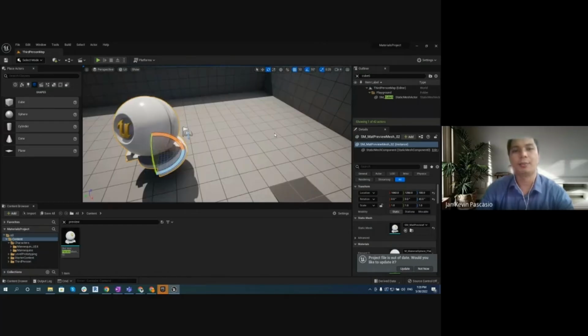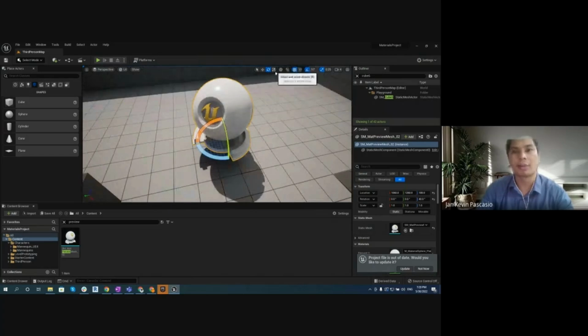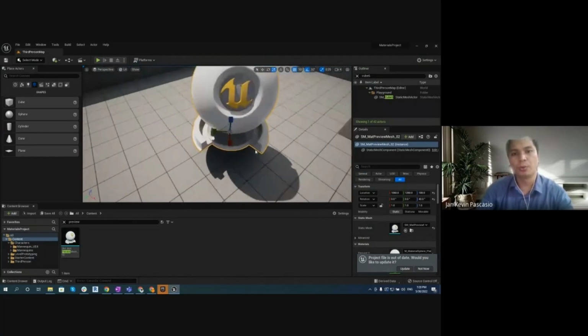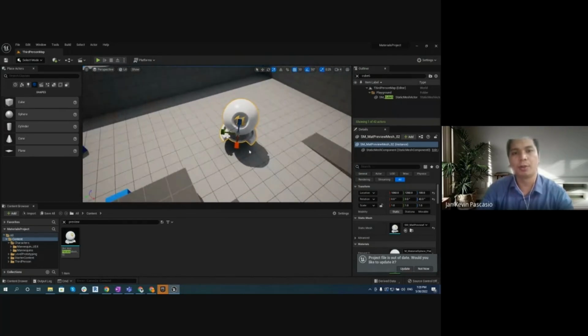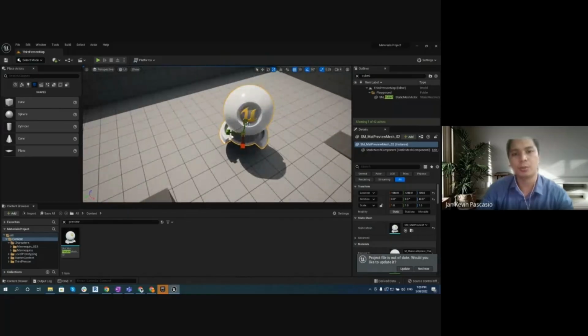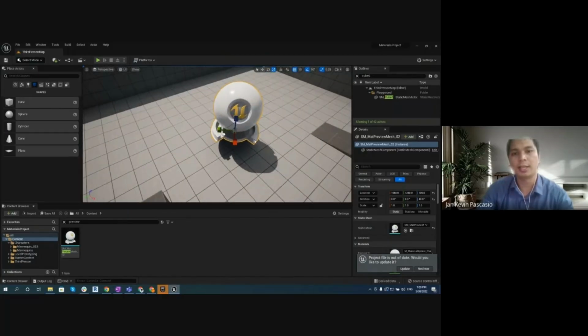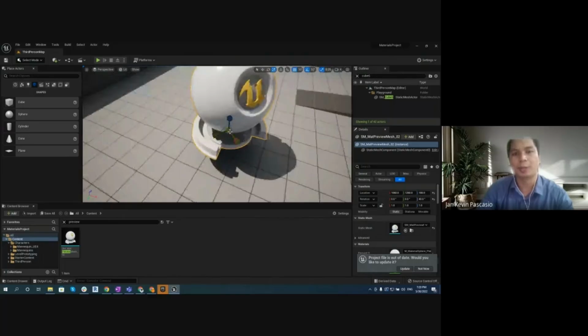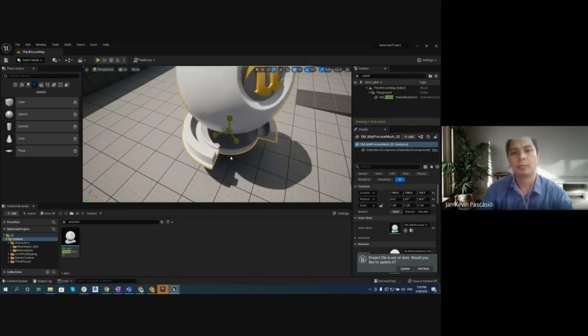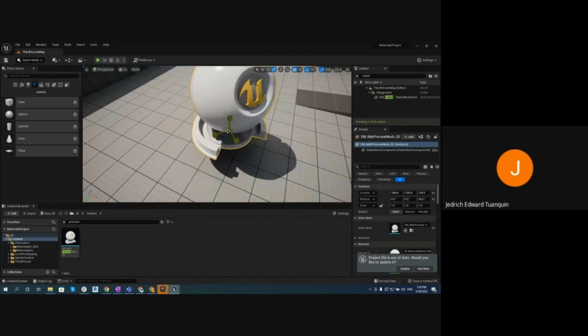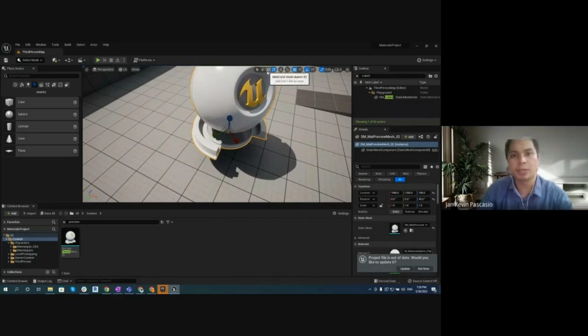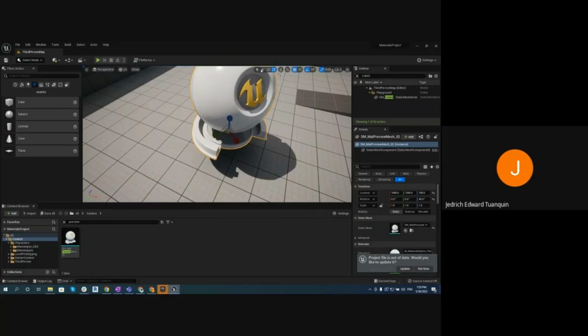And we have the scale, which is press R or click on the button here. So the symbol of your gizmo will change into this. So you can scale an object entirely by clicking on the center of the gizmo. That's 1:1:1 scaling. What button is to rotate again? Click on this button or press E on the upper button here.